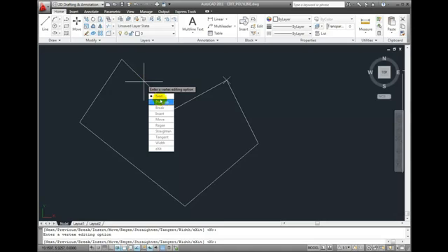If I select the previous option, it moves back to the previous vertex in the opposite direction. So next moves in one direction and previous moves in the other direction. Once I reach the vertex that I want to edit, I can choose one of the other options.